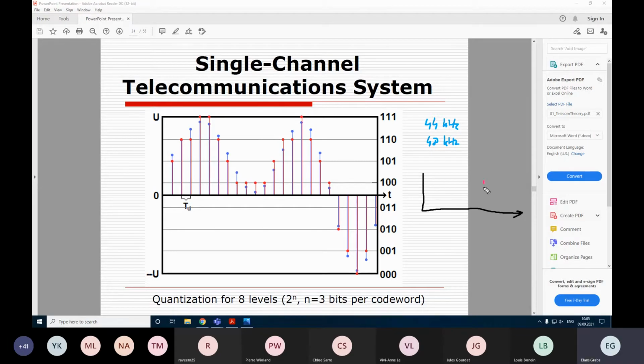Our ears can hear frequencies of up to, usually on average, 20,000 hertz, yes. That is where ultrasound starts. And we again use some filter which cannot really suppress the frequency components starting from this, and has some transient line, yes. So this basically gives us 24 or 22 kilohertz, and that's how these numbers are obtained.